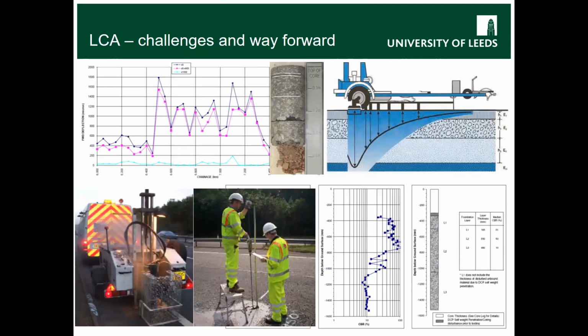And so we really need to communicate effectively with engineers who do the site work and collect the data. That is really useful and actually crucial to help us improve the accuracy of our LCA study. So for example, people use the deflectometer to derive the stiffness of the materials, and based on that, we calculate the residual life of the pavement.